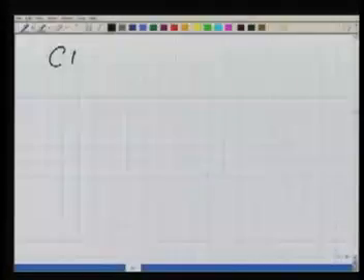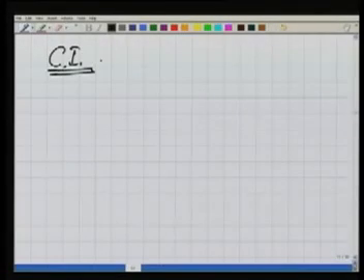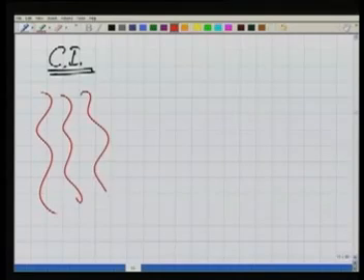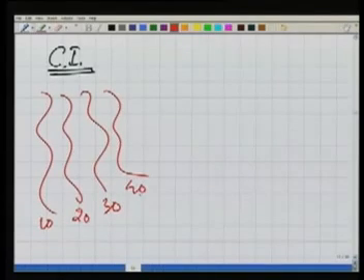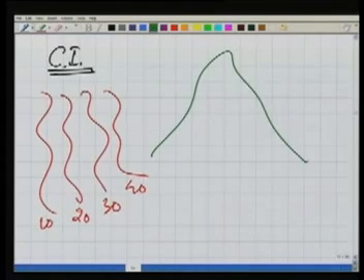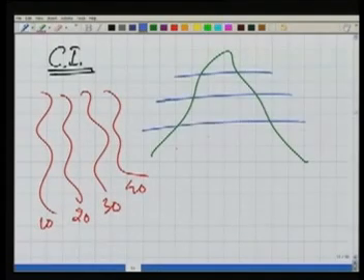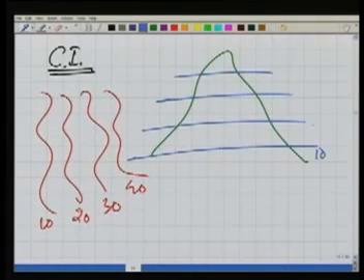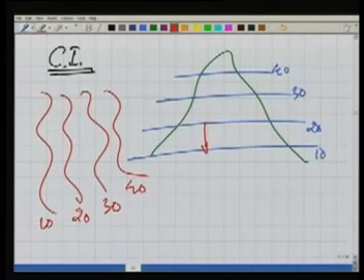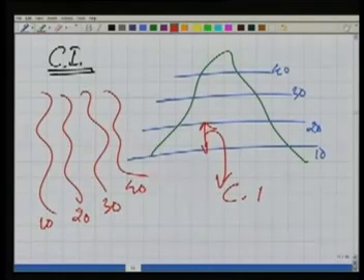Now some more things about the contours. One is the contour interval. As you might have seen, for any contour so far, we are writing them as 10, 20, 30, 40. Basically, if my ground is this and it is being intersected by these horizontal planes of 10, 20, 30, 40, then the height difference between these horizontal planes intersecting the hill, we call the contour interval.